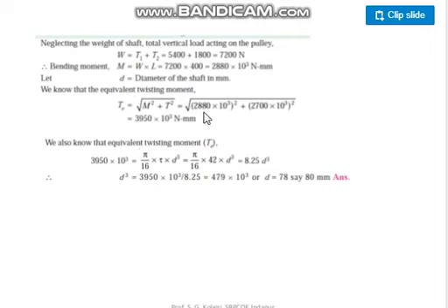This is a little more compared to this. But actually, what is the desirable thing? This one. Again here, equivalent torque we can find out: square root of M square plus T square. From that you will get this one, and this torque equivalent should be more than the torque. You are seeing it is 2700, this is 3950.